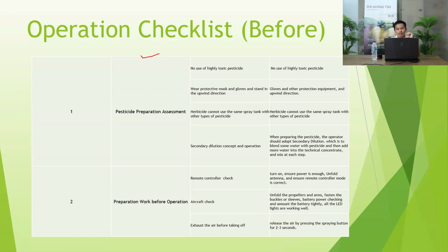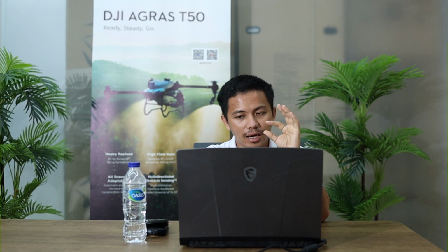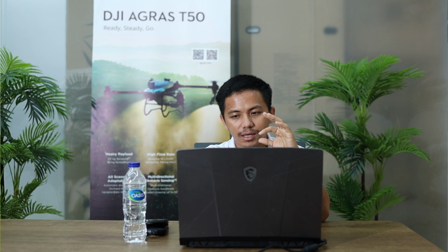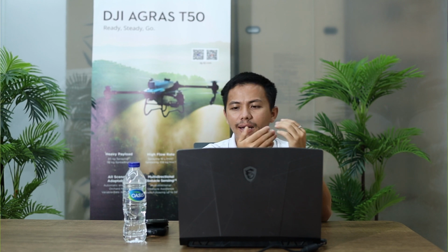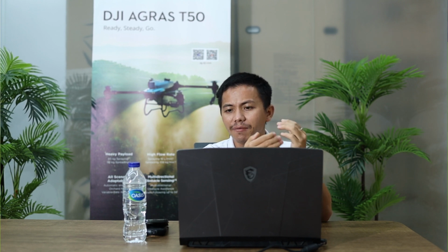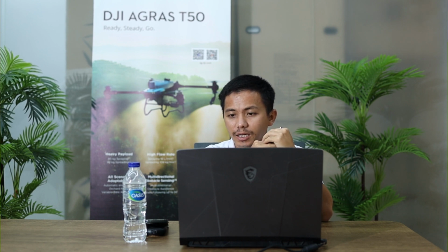Basically, you will see in the drone ESC has LED lights. Most pilots and most operators haven't noticed this LED. You will clearly see it in the manual. So the LED is like flashing red, or flashing orange, or just stable orange, or slowly flashing. How the LED behaves tells you what the status of your drone is. So please check the LED light as well.